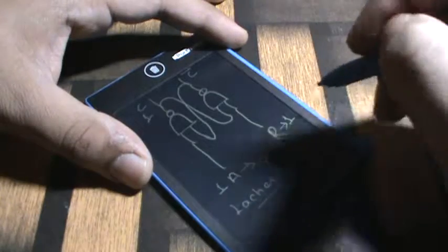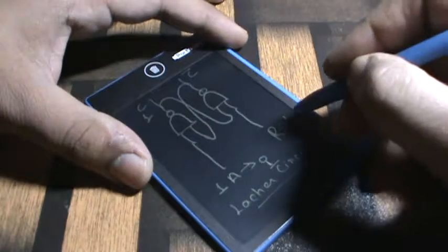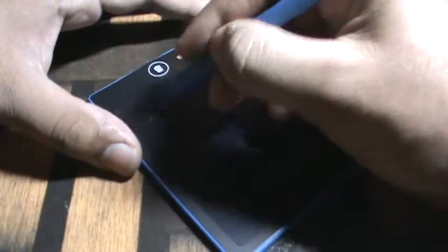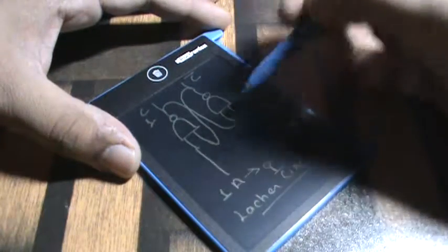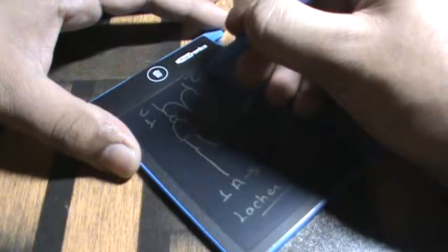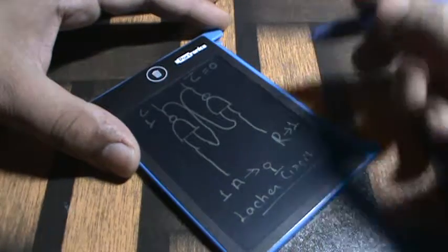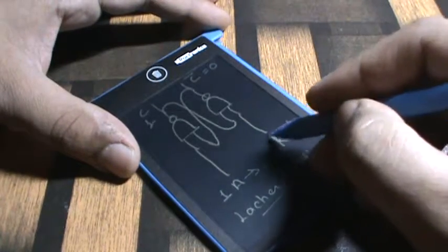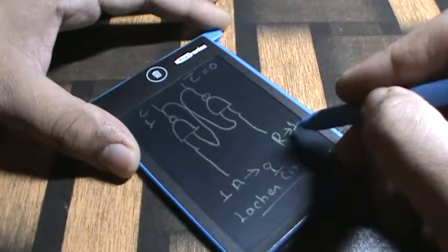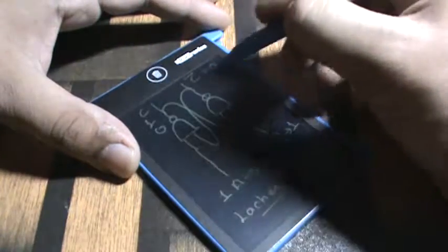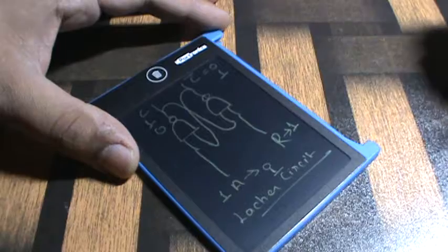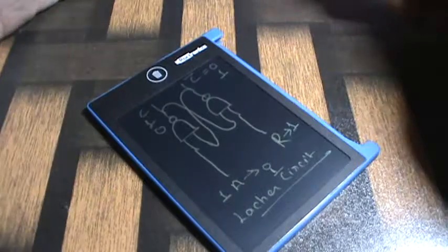I'll tell you in a minute why we call this a reset. When we give 1 on A, C bar, or C inverted, becomes 0. And when we give 1 on the reset pin, C becomes 0 and C bar becomes 1. That's it. That's all it does.